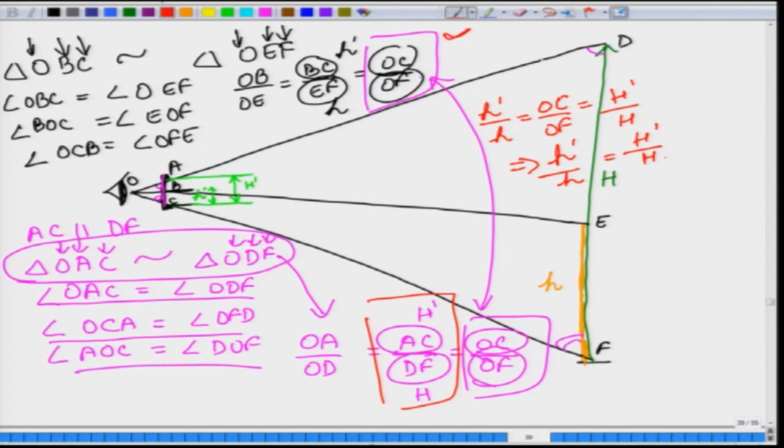Now, in the case of this hypsometer, you know the height of this rod, this one. You know the capital H prime, which is the length of the hypsometer, and you know the value of small h prime, which is the reading that you got from the hypsometer.